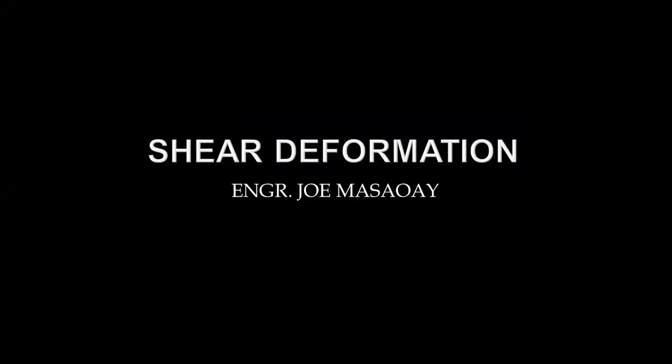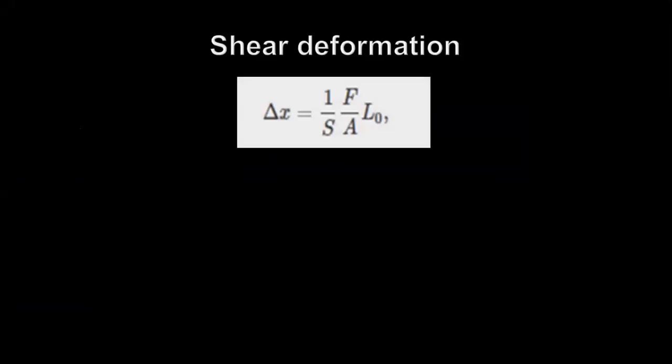In this video, we are going to tackle shear deformation. Our shear deformation is represented as delta x is equal to 1 over S, where S stands for shear modulus, multiplied by F, the force, over area, which is the cross-sectional area A, times the original length L0 of the material,